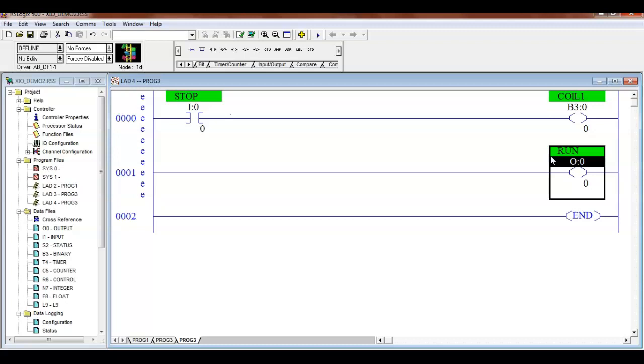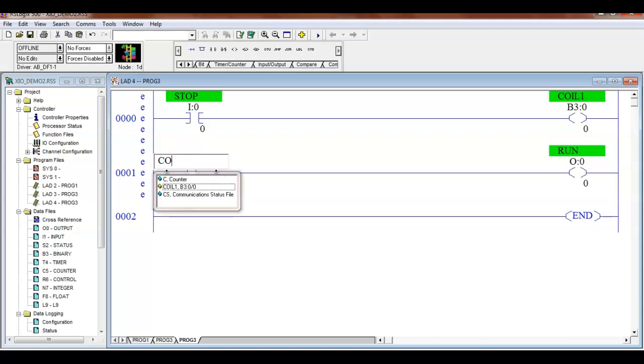6. So here I'm writing a program and I've got a coil that does not need to turn on a light. It does not need to re-energize a relay. It does not need to start a motor. Its contacts are nothing but in my control circuit. If we do this, we're going to use what we call an internal coil. Every PLC supports this. This is what saves money right here.